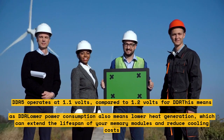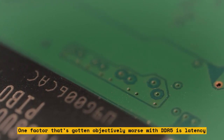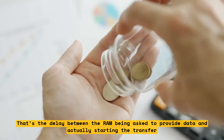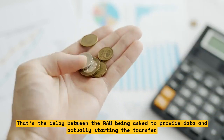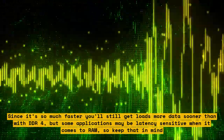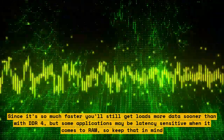One factor that's gotten objectively worse with DDR5 is latency. That's the delay between the RAM being asked to provide data and actually starting the transfer. Since it's so much faster, you'll still get loads more data sooner than with DDR4, but some applications may be latency sensitive when it comes to RAM, so keep that in mind.